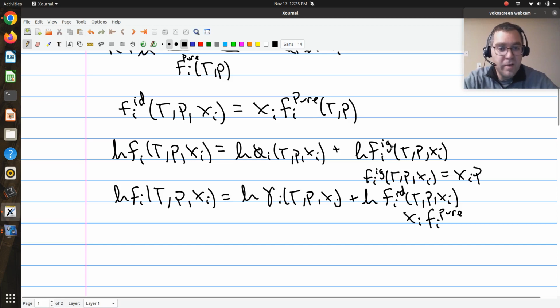So when modeling vapor phases, choosing an ideal gas as a reference state is great. When we model liquids, typically we take the reference state to be an ideal solution. In an ideal solution, we're assuming the intermolecular interactions are all the same. This correction term, which we'll talk about in chapter 12, will account for the fact that my molecules are different sizes and interact in different ways. Okay, cool, that's just my aside.